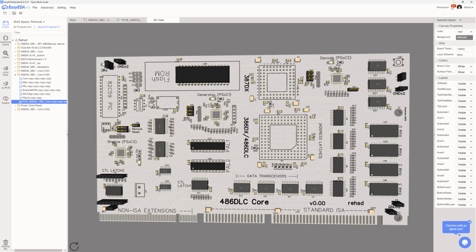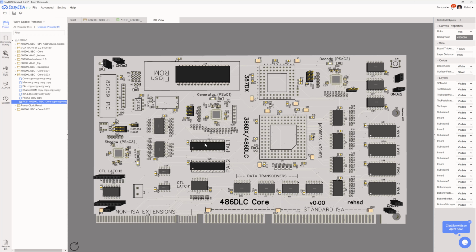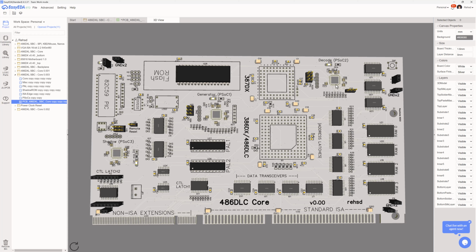So, I did experiment again, front side, back side placement. I didn't find anything on the back side that really made a notable difference. I could compress size, but then it only increased issues on routing. I do have the PSOCs pulled off of their prototyping carrier board, placed right onto the PCB. So I think that is going to be a really nice change, not having to deal with the small PSOC carrier boards. So we'll see how that goes. I'll get to practice soldering around that type of placement, which will be interesting.